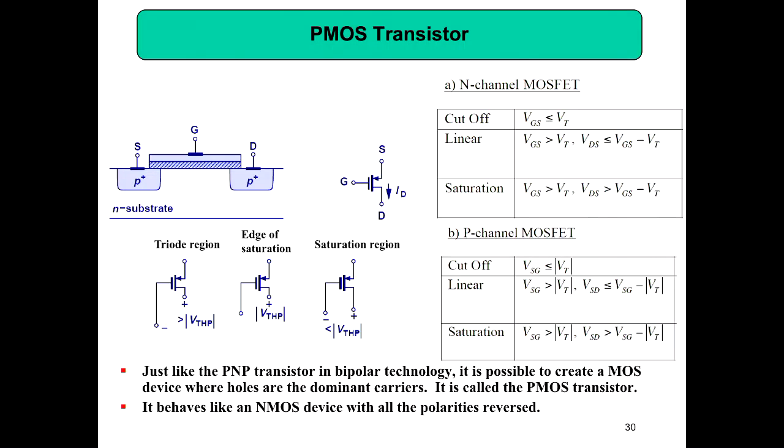Have you thought of it? There are already, it's an N substrate, so there are already the electrons there, sir, in that region. So there won't be any chance because the majority charge carrier will be, for this case, electrons. Okay, so he partially answered, then there can't be a channel formation because channel means you are making a channel. You know what I meant? There's a difference. There are already electrons there anyways because majority charge carriers will be electrons there.